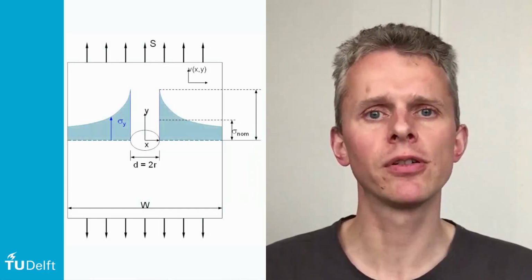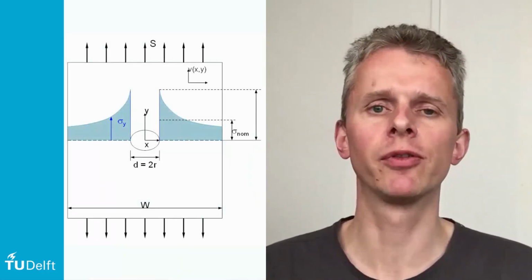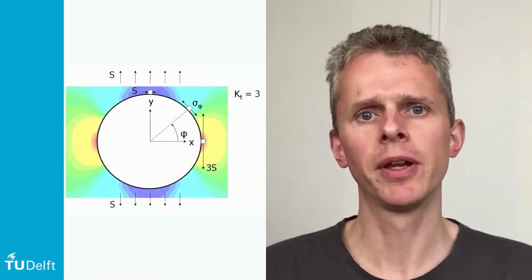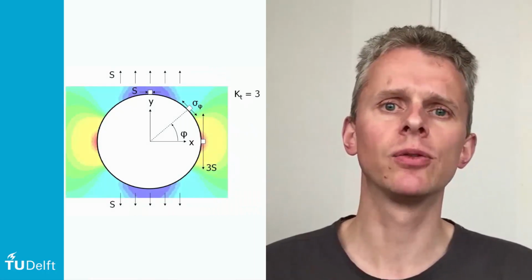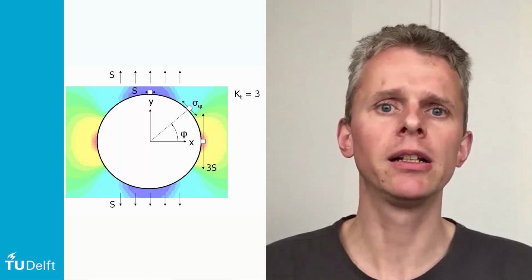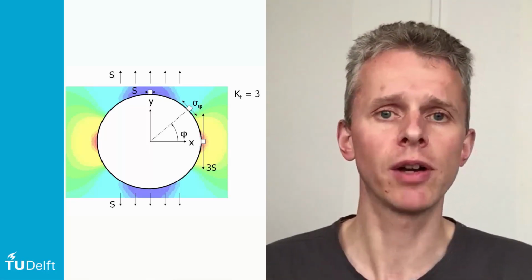In a previous video we looked at the stress concentration factor as a parameter to describe the influence of the geometry on the fatigue performance of a structure. We looked at what causes a stress concentration. I gave you a definition, but that definition related to a notch in an infinite plate, because then mathematically the stress concentration can be well described.